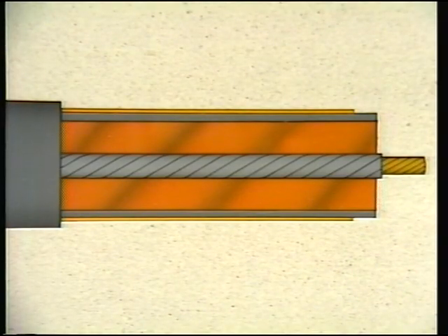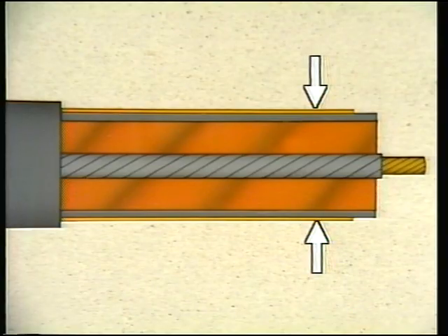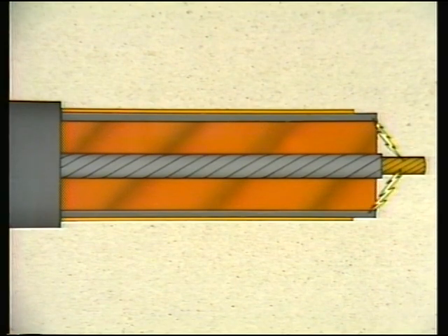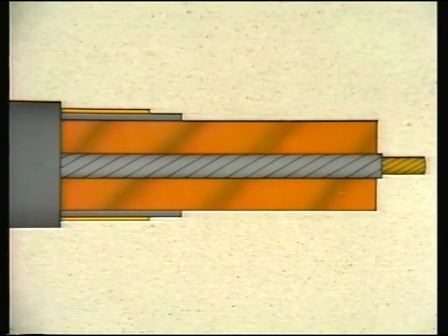This is an illustration of a primary cable with the cable jacket removed. When a cable is terminated, the semiconductive insulation shield, which is in contact with an electrical ground, must be kept at a safe distance from the conductor and connected equipment to avoid a direct path to ground. So the semiconductive insulation shield is cut and moved away from the end of the cable conductor.